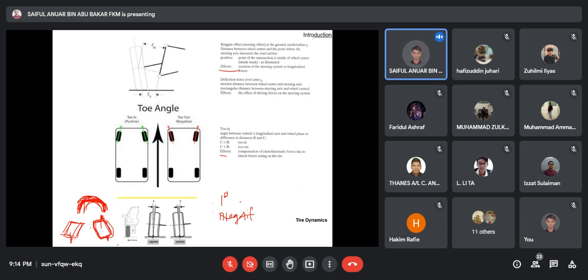Let's say the tuning of the camber angle for the rear axle is wrong. For example, the Proton Pave has a bad configuration for the camber angle. Based on user comments and complaints, the rear tires tend to wear very fast.